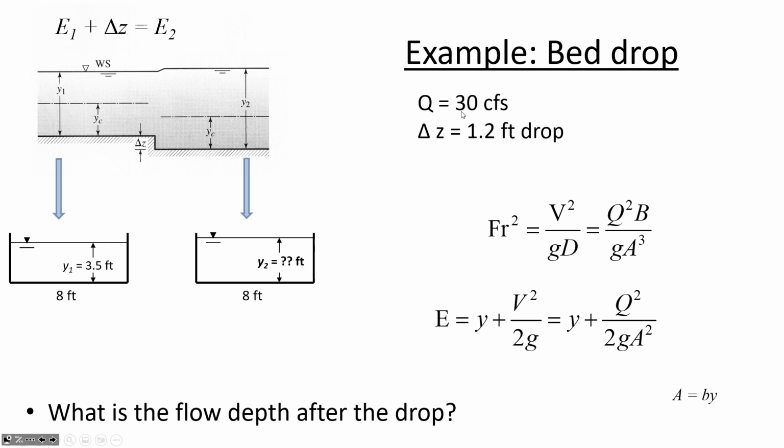I think the Casio calculators have a specific mode that's set aside for solving cubic equations, and it'll give you all 3 roots. In this case, the roots are negative 0.211, 0.220, and 4.708. Now we can automatically throw out the negative flow depth. That doesn't have any physical significance. But the other 2 flow depths are each depths that give you the right amount of specific energy.